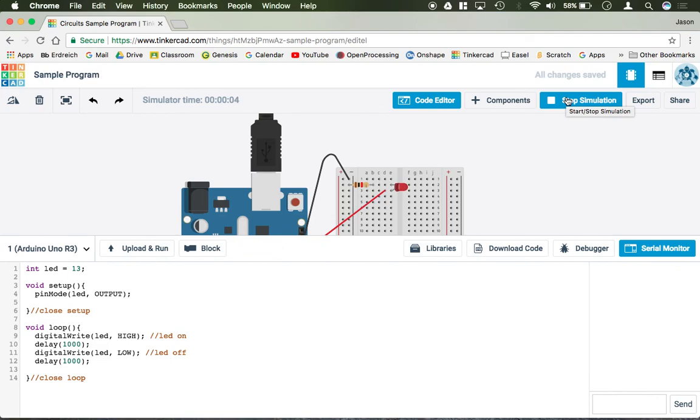That's the fundamental basic for doing a digital output. You have to set your pin mode. You don't need to use a variable, but it's more convenient and more organized if you do. And then use the digitalWrite command to go ahead and create your digital output.